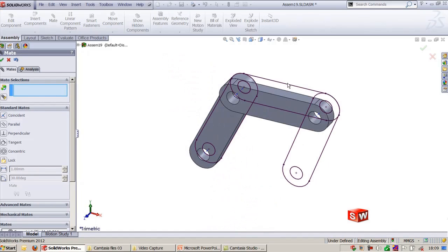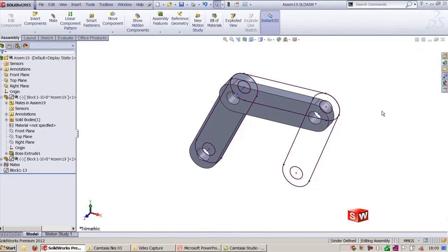This is how you can use layout sketches to create virtual components in the assembly environment. So what exactly is this virtual component? When you are creating the design in the top-down approach, that is, you have only the rough sketch and you are going to create parts, and you are undergoing a number of iterations, then definitely this approach will help you to create the model, because the part will be saved internally, not externally. If required, you can make it an external file.